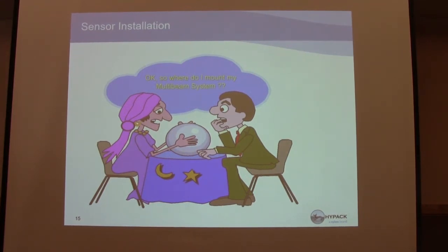And I would make sure that it's got a couple of really nice connection points where it doesn't vibrate during the survey. Because what we see, it's an environmental issue that we always are talking about with our customers, is when the boat is underway and the sonar is over the side or over the bow, it can be vibrating if you don't have 2 or 3 points of contact of the pole to the boat.